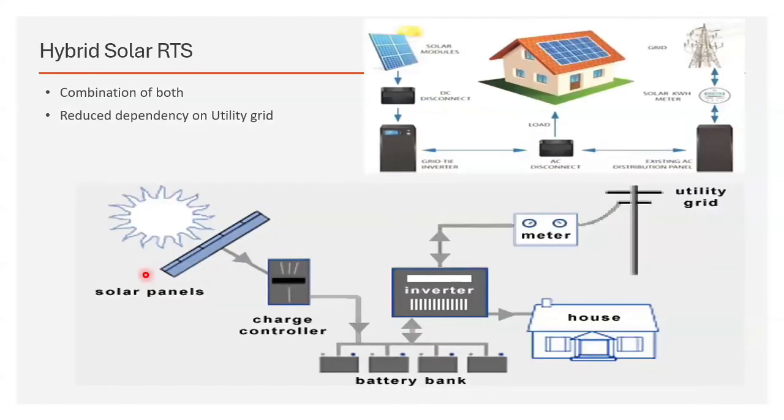Next, hybrid. Hybrid is a mix of that. Here there is an inverter, and there is a battery bank associated with it. In this case, we have to install a solar panel that should be greater than our system demand. Suppose my household load is 1 kilowatt, and we install a 2 kilowatt solar PV system. Then the 1 kilowatt instantaneous demand of the household load will be catered by this solar system, the remaining will be used to charge the battery bank, and the excess power will be fed back to the grid. During night hours or after the evening, this battery bank will support till it is drained, and thereafter we have the option to draw power from the utility. It's a better system, but since a battery bank is involved, maintenance becomes a concern. We need to maintain the battery banks here.